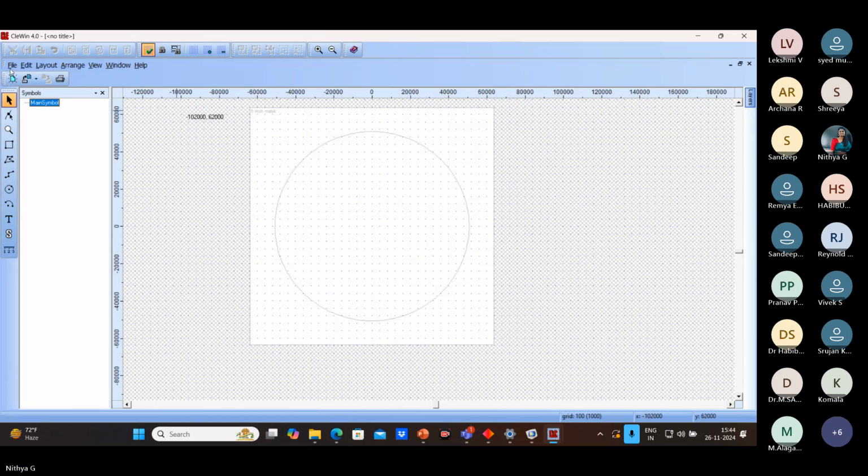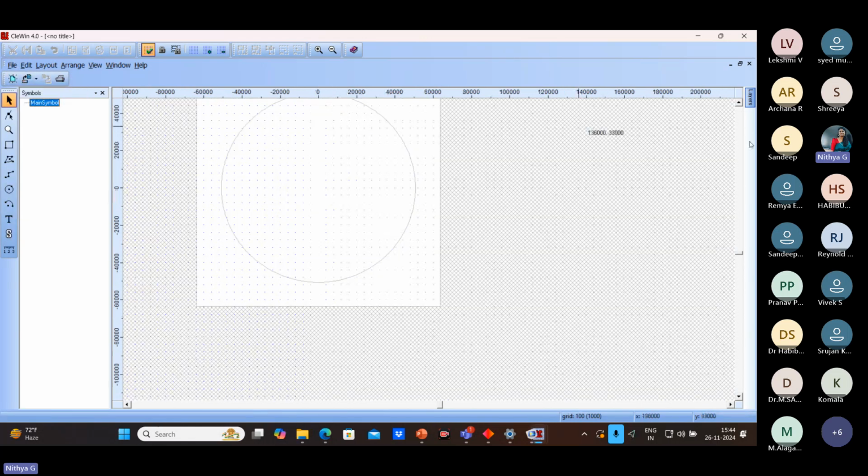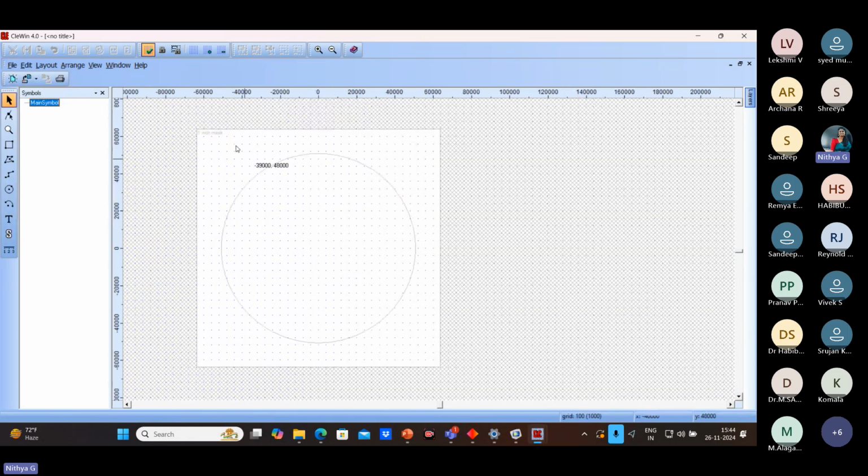So I have to create a new file. So I created a new file, right? And then this is giving a 5 inch mask with the 4 inch wafer. Then if I see on the leftmost corner, this is the edit objects. So this is for the selection. And if I have to edit a few nodes, so out of a square, if I want to move one or two nodes to the next point, right?